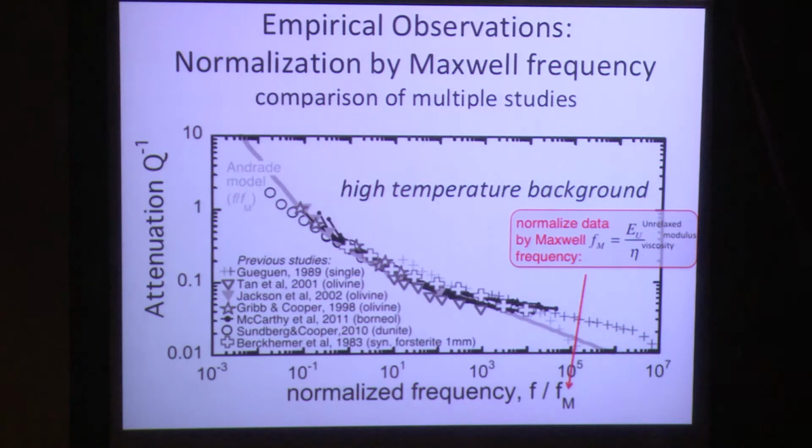And that's not only powerful in comparing different materials, because what this tells us is there's similitude. Polycrystalline materials have this same response. And that tells us that the same mechanism is acting, with the same time scale or response. And that, we believe, is grain boundary sliding, the diffusionally accommodated grain boundary sliding. And again, these were all carefully created to be at very low stress amplitudes, and to have no dislocations in them before, which we could talk about later, how realistic is that. I think to the first order, it's a really good approximation.